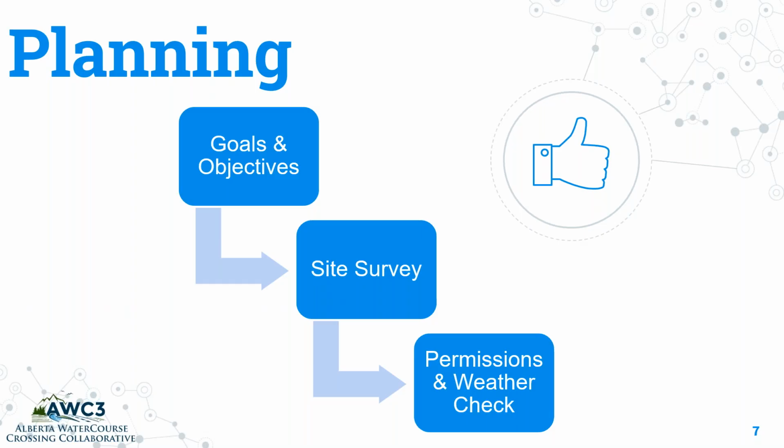The next would be to have a really good idea of what the site looks like that you're going to be working on. How homogeneous or heterogeneous is the environment that you're looking at? Because let's take for example, you are looking at a very homogeneous environment such as a gravel pit. Well, when we talk about photogrammetry, seeing as it is trying to tie pictures together using common tie points, it is hard for the post-processing software to be able to identify one piece of gravel from another piece of gravel.